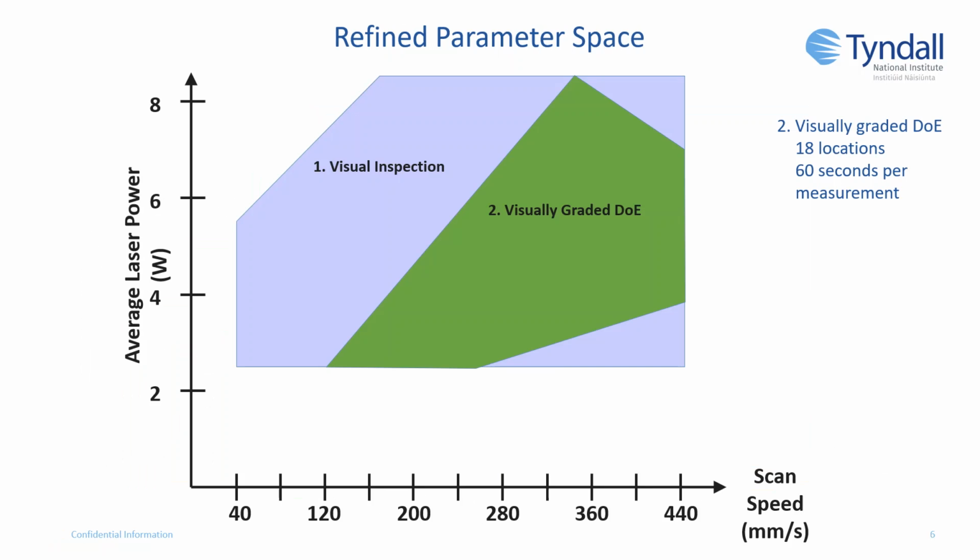This viable region, marked in green here, was used as the maximum values for a design of experiments response surface. For those unfamiliar, design of experiments is a set of statistical methods that vary multiple experimental factors simultaneously and measure one or a number of response variables. This allows for the reduction of spurious factors to highlight the core and dominant dependencies of a process.